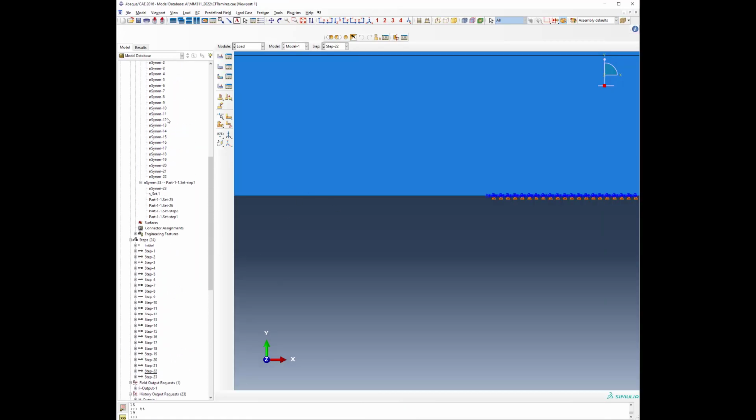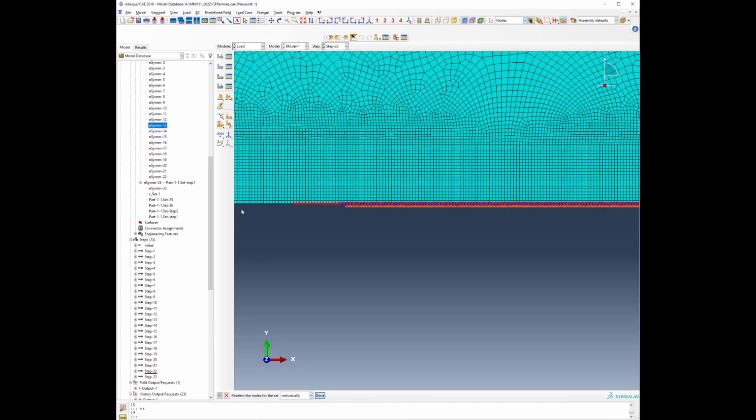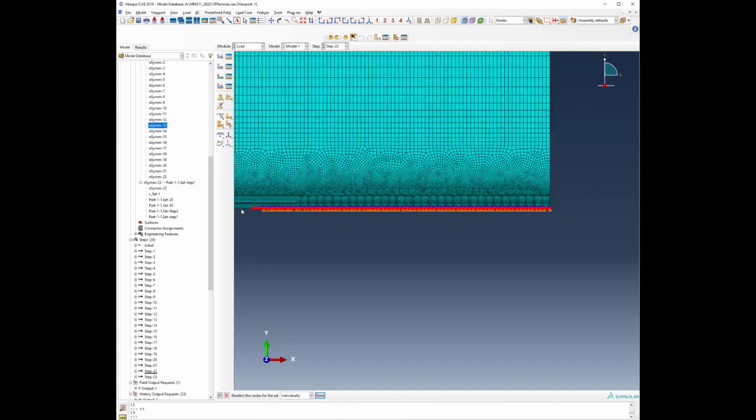So if you see, this is the node set, okay, and so when you want to make a node set, you select this by dragging your mouse, which makes a box, and the same thing can be done by coding it using the getByBoundingBox command in Python in the Abaqus script.